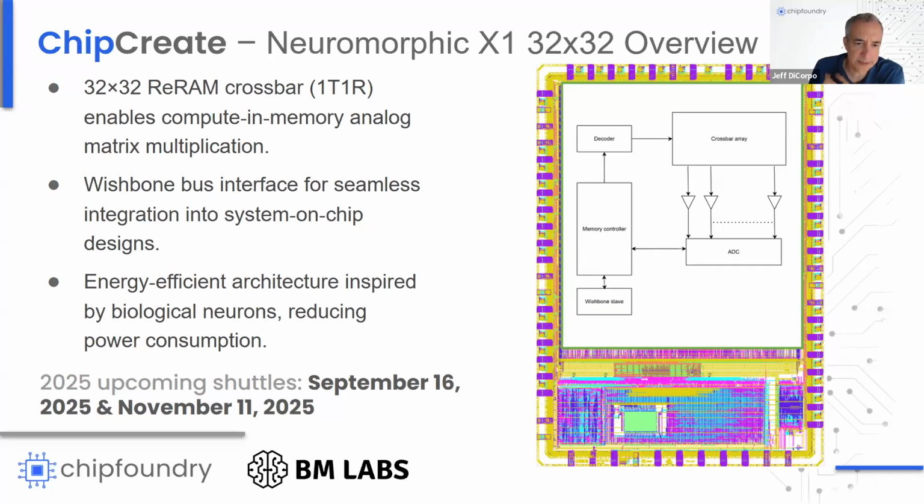Okay, is there a bit in the data bus that indicates whether they're doing a read or a write? Yes, there is. You're correct about that. Our wishbone data bus is 32-bit, and in the example I only talked about the 27 and so on. The initial 2 bits are the mode set. If you see our data sheet, it will determine 00 is set, 01 is reset, like the write and read. So these bits are used for indicating what you were just asking about.